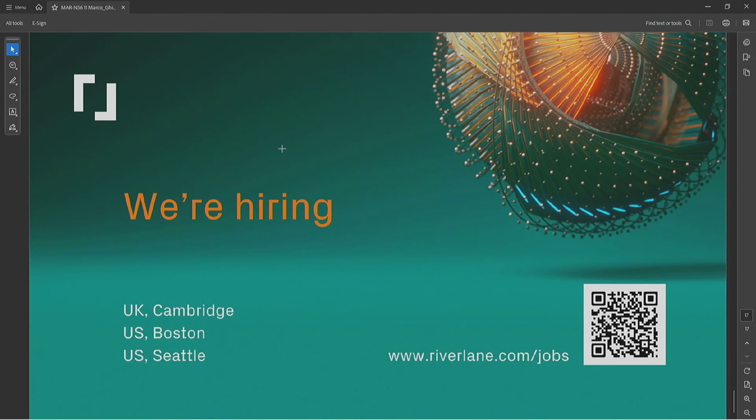Yeah, it's a good question. We estimated the bandwidth that we need. The way we did it was we expect 1,000 qubits to be covered by one system, by one link. Then we are strong on soft information, I don't know if you've seen our work on that, which allows us to increase the number of bits per measurement to up to 8 bits.